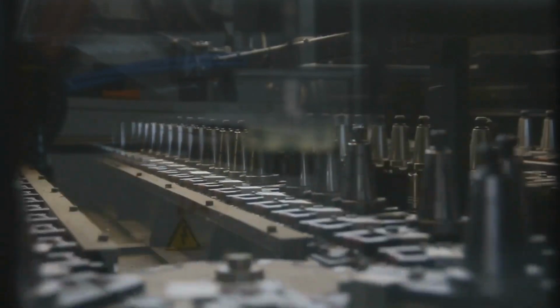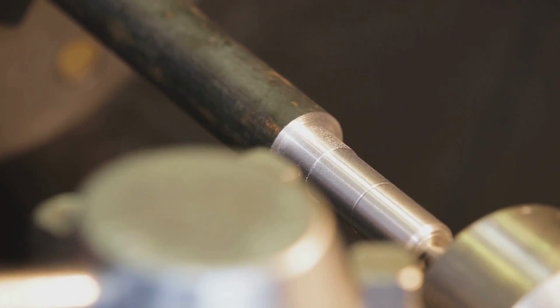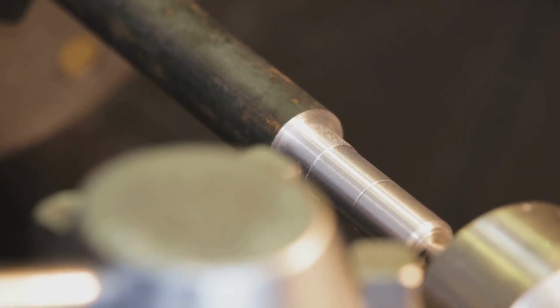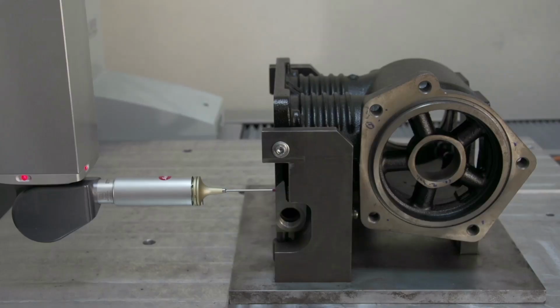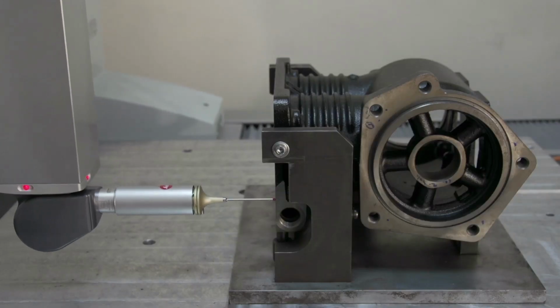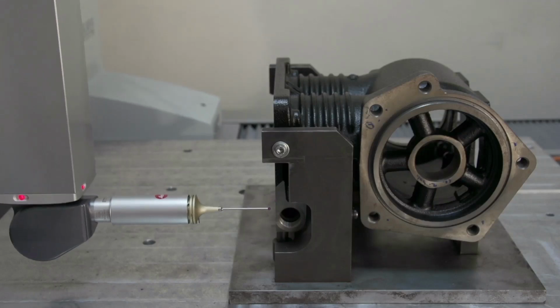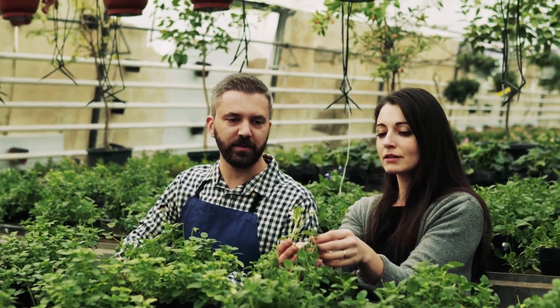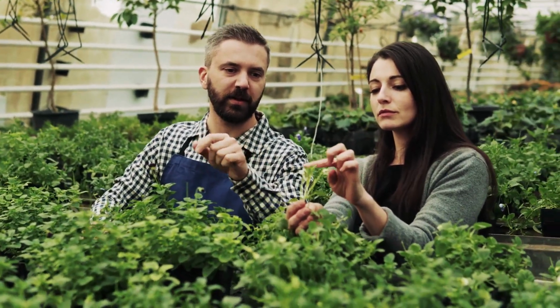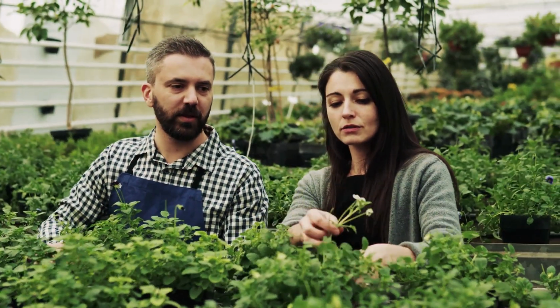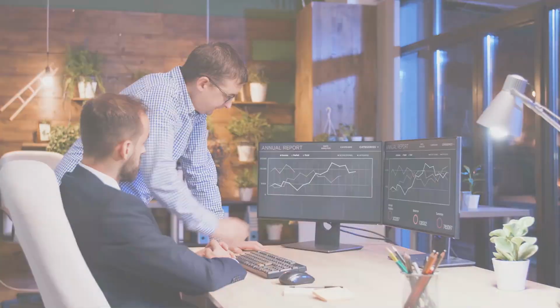For example, consider a manufacturing process that produces screws. If the diameter of the screws fluctuates slightly within acceptable limits, that's common cause variation. But if one batch is significantly larger or smaller, that's special cause variation, which warrants immediate action. The main goal of SPC is to keep processes stable and predictable by identifying and eliminating special causes of variation.